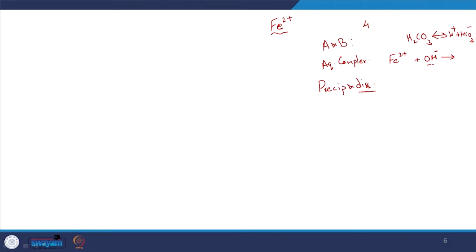The compound can be dissolved, or if it's in far excess of the stoichiometric ratios, precipitation can occur. So, in that context, where did we come across this? I guess we looked at lime softening, where we were trying to remove calcium by precipitating it out as CaCO3 solid, or magnesium hydroxide as a solid. We came across this earlier, the application of precipitation.